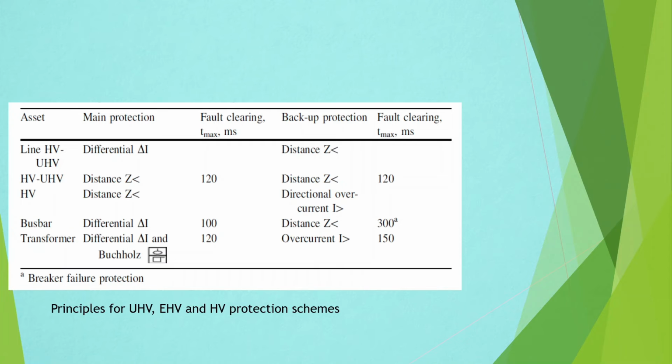The protection function is based on the fact that along a fault free line, the ingoing current should be equal to the outgoing current. However, the current flow along the line will be influenced by the capacitive current. Therefore, the difference of the ingoing current I1 and the outgoing current I2 of the fault free line is not exactly equal to 0. A small difference will be measured for unfaulted lines. A stabilizing current is introduced to avoid an over-functioning of the differential protection.